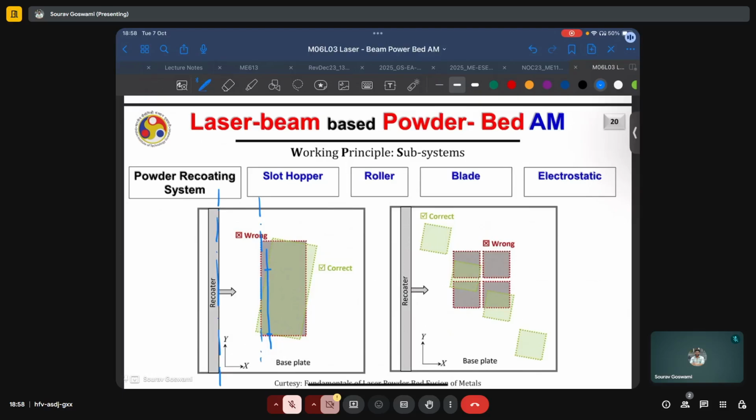In the other case also, where we are printing multiple parts, instead of aligning them together very neatly, we should stagger them, again slightly tilting them from the recoater axis based on the principles we just discussed, but also spreading them out to prevent a propagation of errors. Because if for some reason the recoater or locally there is some damage or some error, then it will get propagated over the powder layer and can affect also other neighboring parts.